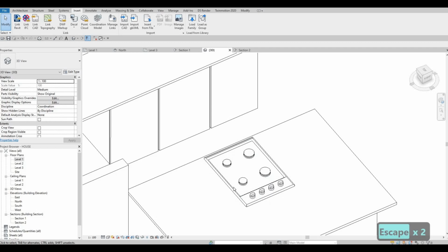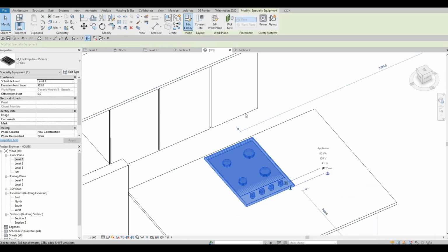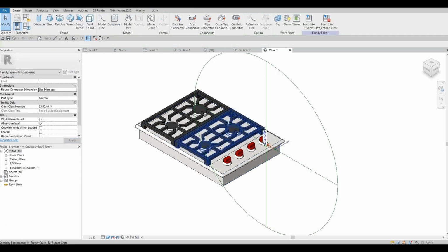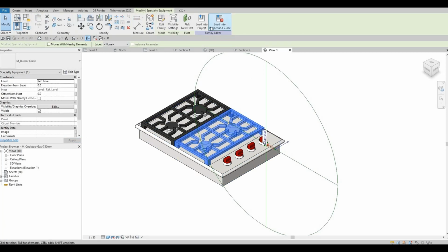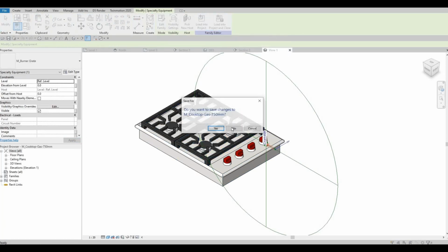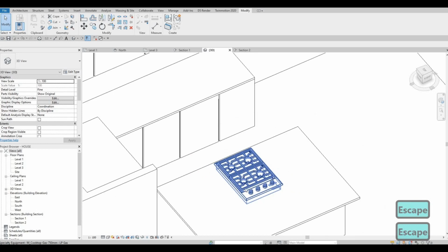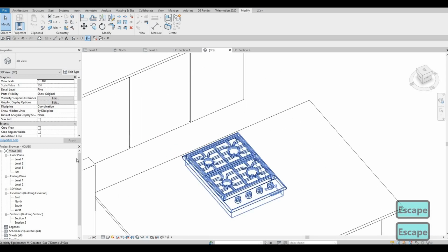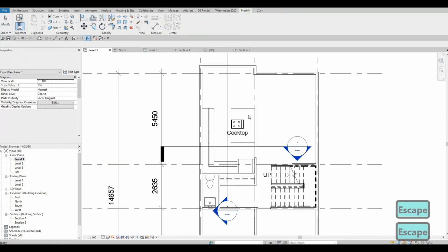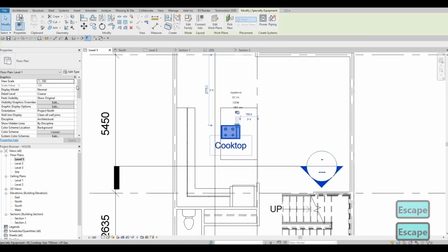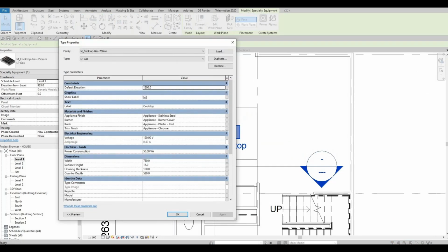Okay. It's just weird that I just want to double check this. This one is not appearing. So I know what to do now. It's not appearing because we need to set it to fine. There we go. And then let's go to level 2 and then just edit, uncheck this.